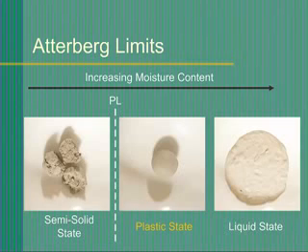When a soil has a moisture content at its liquid limit, it is at the boundary between plastic and liquid behavior. If water is removed, it will act like a plastic material that will be moldable and deform without cracking. If water is added, it will act like a viscous liquid that can ooze and flow.